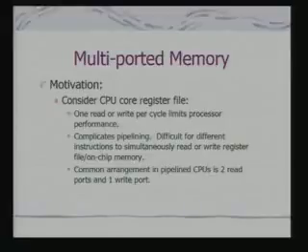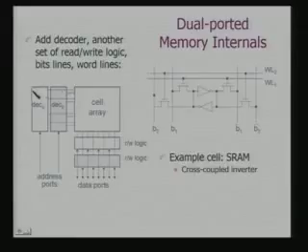So you can see that we have in some cases dual access memory, single access memory. In dual access memory, 2 read ports and 1 write port is a common arrangement. So there are simultaneous reads from the memory block. So effectively, what does that mean? If I am talking about a multi-port or dual port, effectively it means that I have additional decoders. The 2 decoders, because there can now be addresses coming from 2 distinct buses, because there can be 2 simultaneous read accesses from a memory block.